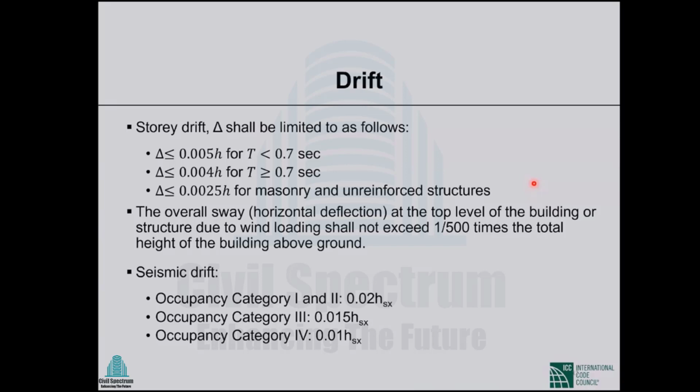That is not the case. It depends on the mass and stiffness of the structure, and the same structure, whatever the amount of force you pull it with, will take the same amount of time to make one cycle. If you want to understand more about this, you have to study structural dynamics. So just know that every structure has its own period, and we can calculate that period.